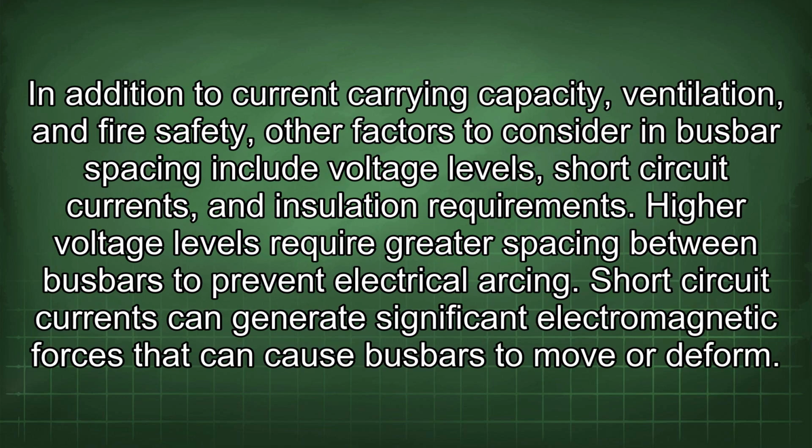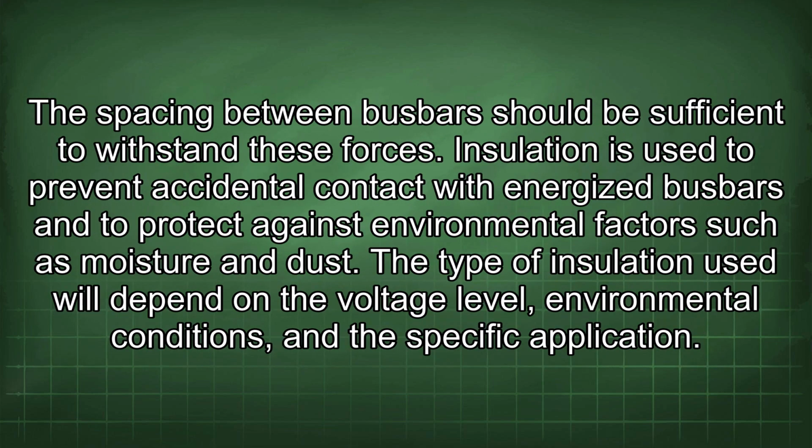In addition to current carrying capacity, ventilation, and fire safety, other factors to consider in busbar spacing include voltage levels, short-circuit currents, and insulation requirements. Higher voltage levels require greater spacing between busbars to prevent electrical arcing. Short-circuit currents can generate significant electromagnetic forces that can cause busbars to move or deform. The spacing between busbars should be sufficient to withstand these forces.